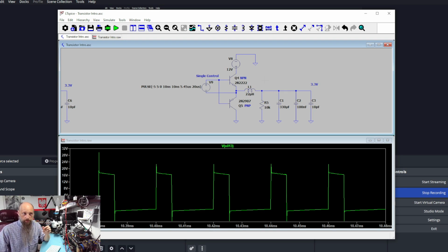That's why it's very important to check Q4 if it's not shorted, because if you connect your meter to 12 volts and to the ground, it might not tell you that there's a short, because Q5 is still working. Q5 is still not open, but Q4 is a piece of wire. Again, if you connect the CPU, supply 12 volts, all that 12 volts will go directly to the CPU, frying it in turn. So to sum up, our transistor is not exactly like a switch,